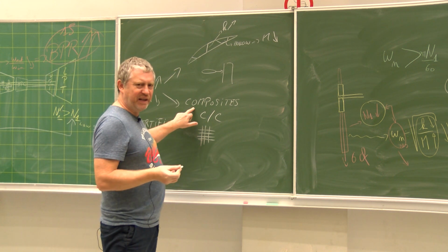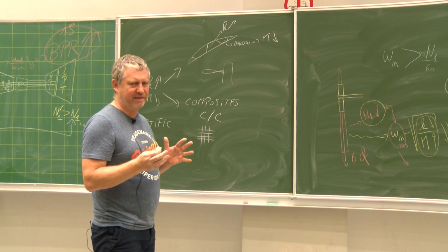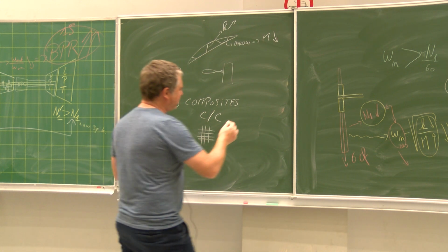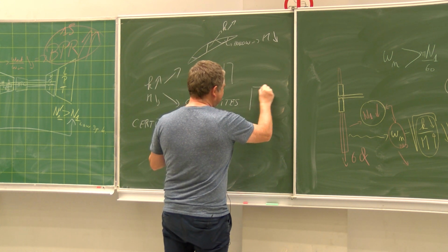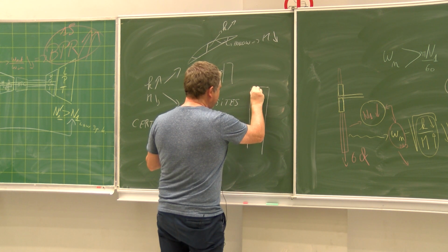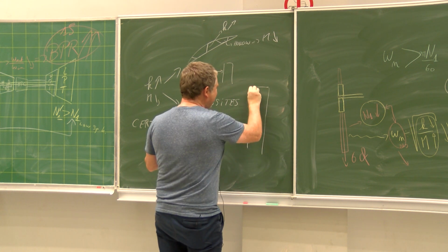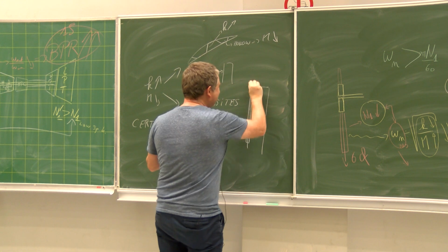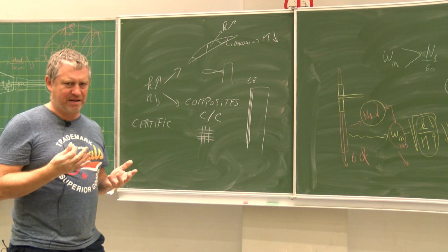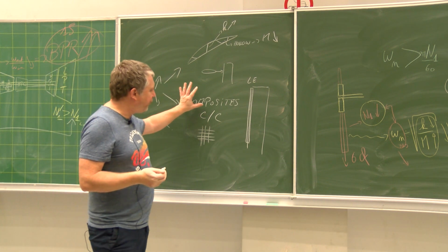And composite materials are very bad for that. They are not good against impact. And so that means that on these blades, these are huge blades, you absolutely need to put on the leading edge of the blade a reinforcement that is metallic. So it's not a fully composite